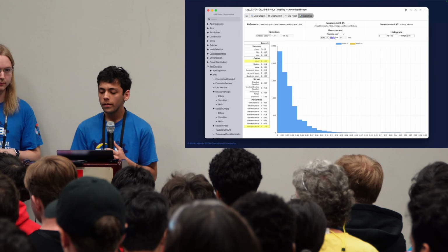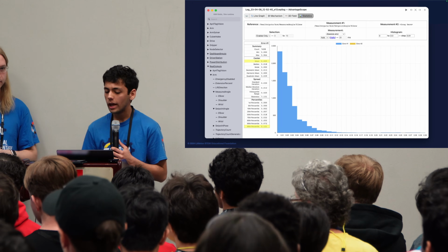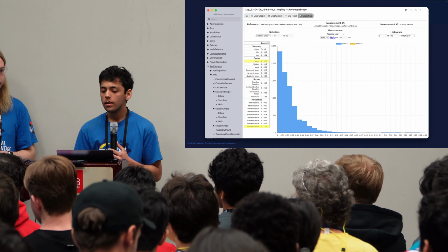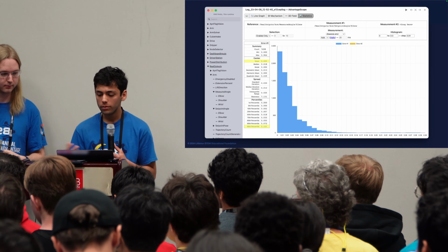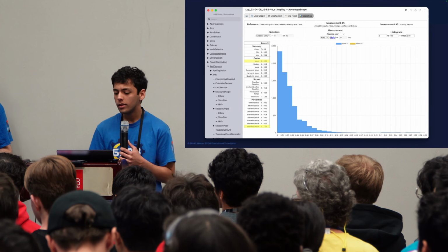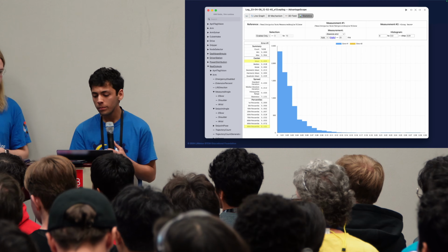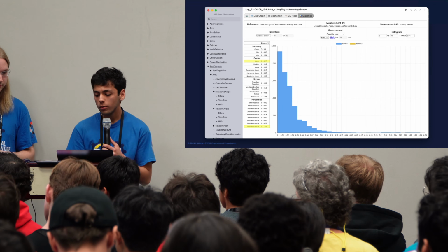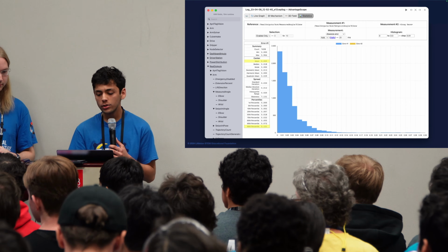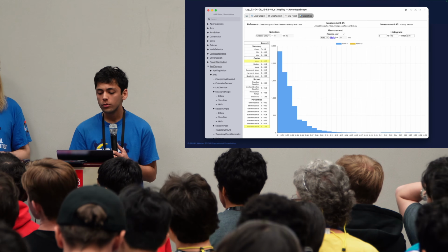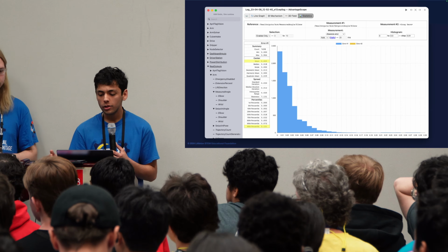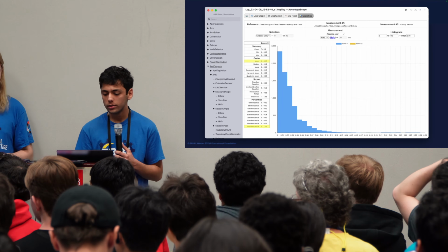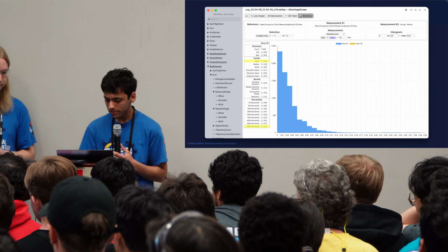views such as this. AdvantageScope will automatically calculate the absolute error based on all the measurements between the set point and the live recording of the motor encoder or whatever you're using. And here's the average error for our 2023 arm for the elbow across the entire match. You see that the mean is around 0.025 radians or 1.4 degrees, which is pretty good, as well as the 99th percentile of error being around 7 degrees or 0.121 radians.